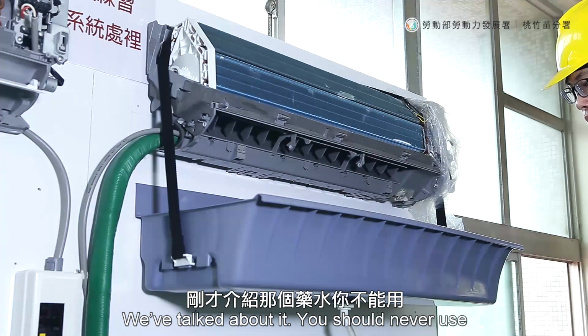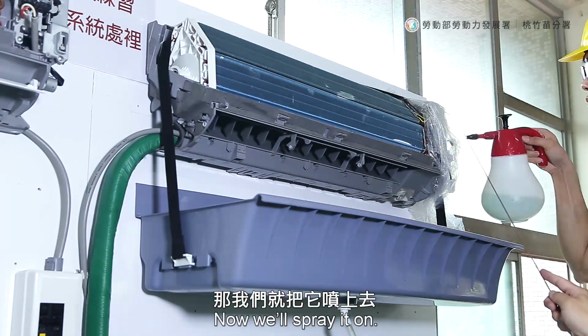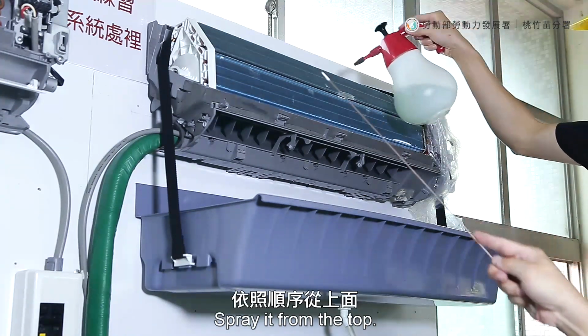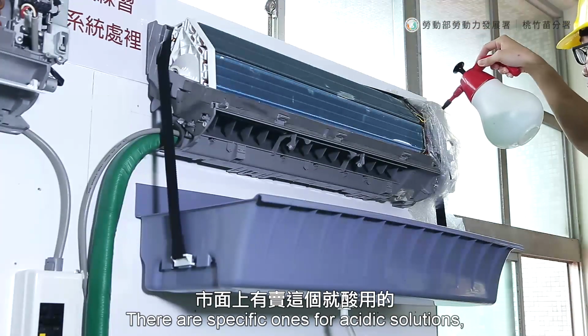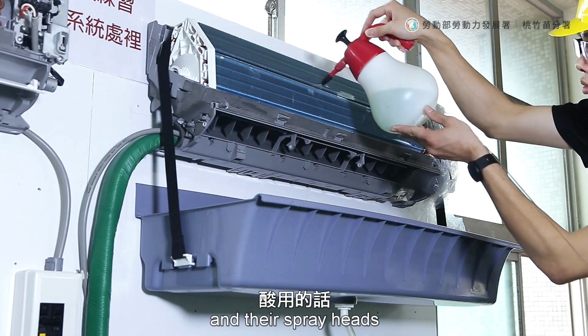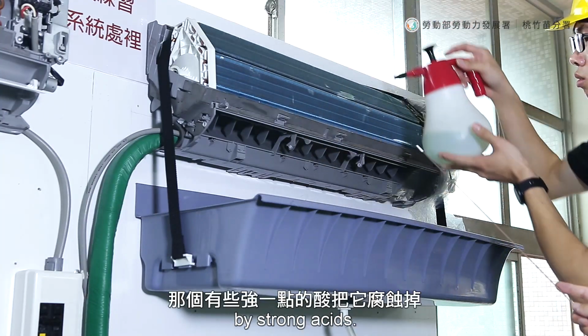You should never use strong acid to clean the AC. Now we spray on it. Spray it from the top. We can use a pressure washer. There are specific ones for acidic solutions, and their spray heads won't be corroded by strong acids.